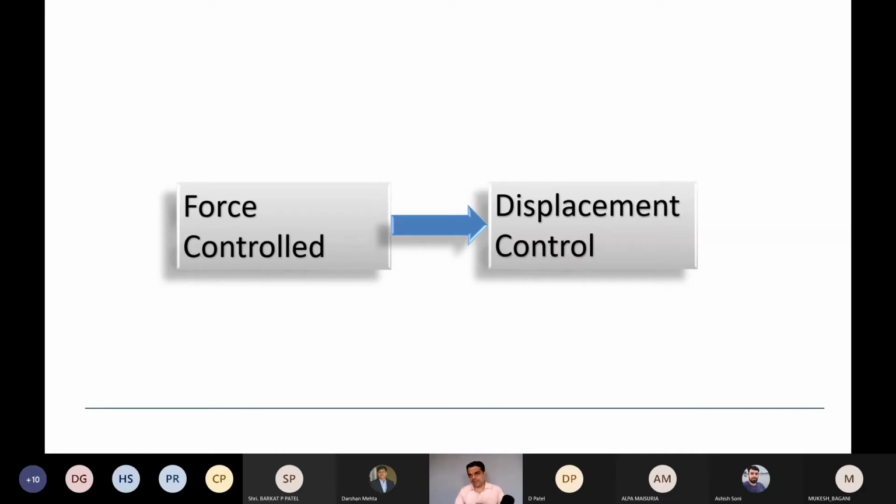Okay, and now when we refer to IS 1893 Part 1 2016, the same soft story is now dealt with separately. What is written now is that the 2.5 times amplification factor is removed, and instead it is suggested that we should provide a shear wall, and there are also requirements of drift control, which is identified for the different kinds of other irregularities also. So the ultimate goal is that the displacement or the drift should be controlled. So this is what I believe, that now we are transferring towards the displacement control side.